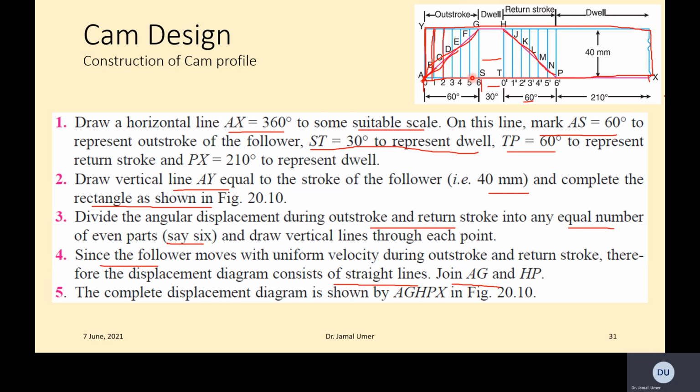So it goes for valve opening time and closing time, the valve timing. We know for how long it has to open and for how long it has to close. What should be the speed of closing and opening? All this depends on the engine, the piston movement and the cylinder size, because we want complete removal of exhaust gases and intake as maximum as possible.